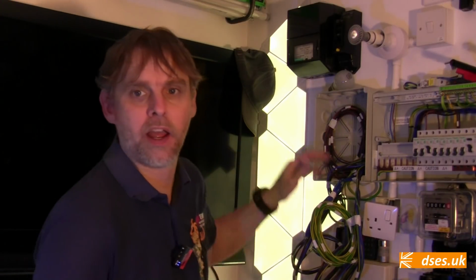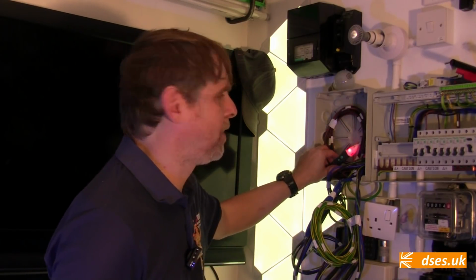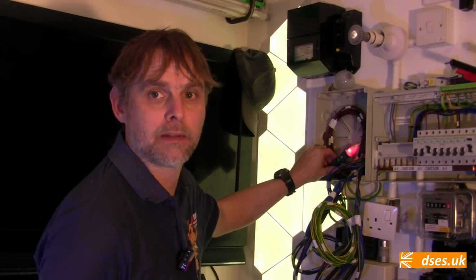Here is a demonstration of how I am part of the non-contact circuit. For those watching who already do site work, how often has this happened to you? You have an energised wire and you want to go back to the board to clock off the breaker, only you don't know which breaker it is. As an audible aid, you want to leave your non-contact detector next to the live wire so you can hear when it stops sounding. So you balance it by the wire and you get it tootling away and then you make to leave. Oh, will you look at that? It's right next to a live wire, but it's showing dead.